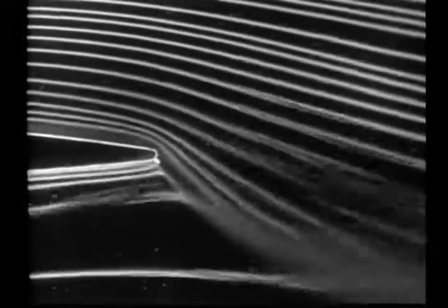Each element of the jet sheet is subjected to a centrifugal force, which is in turn just balanced by pressure forces. The curved sheet thus supports a pressure difference, much as if it was a solid flap. This is reflected on the profile as a change in circulation.